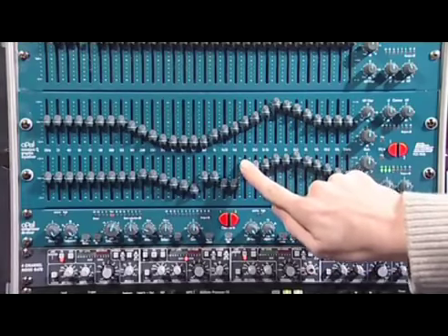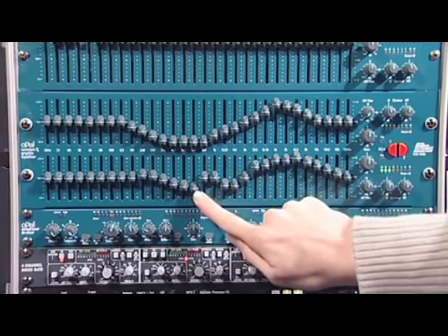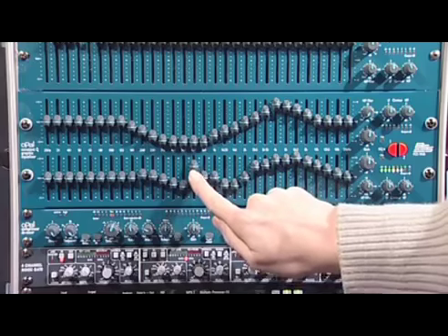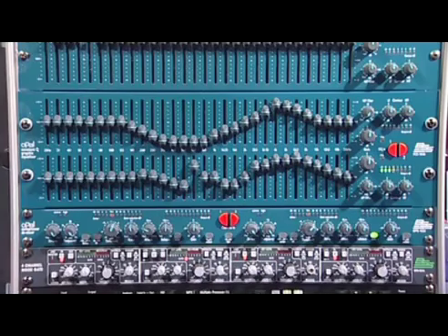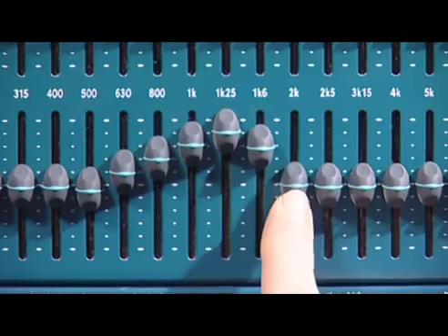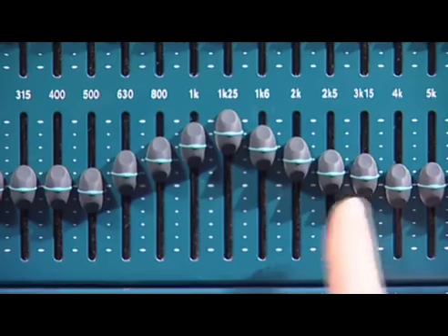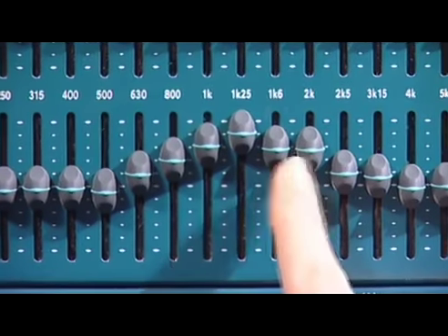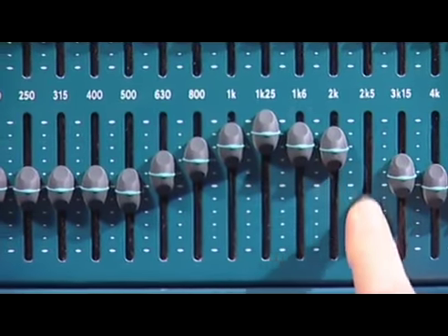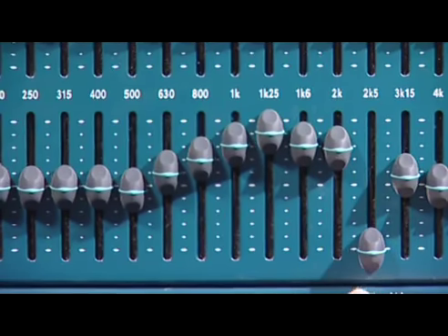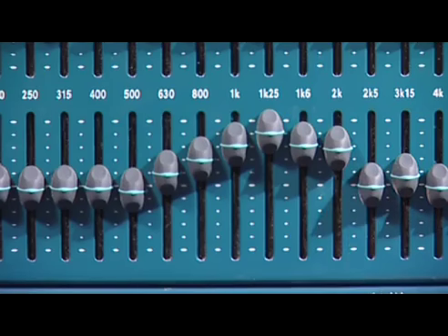Graphic equalizers can cut or boost a large number of fixed frequency bands. They're called graphic equalizers because you can see the shape of the EQ curve from the position of the controls. Even though the frequency bands are fixed, there are enough of them for you to be able to focus fairly precisely on one or more problematic frequency. They're especially useful for isolating and notching out feedback frequency hotspots and for generally improving the sound of a live venue.